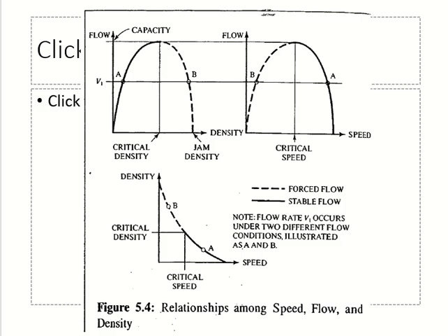So there is a portion or a stage in which the vehicles are on the road and they are moving smoothly, no problem. This is this portion. So you see an increase in density and an increase in flow as well. Then you reach a point after which the density is increasing, with more vehicles being added to the space. But now they are not letting each other move. There are so many, they are blocking each other now. So density is increasing, but the flow is decreasing.